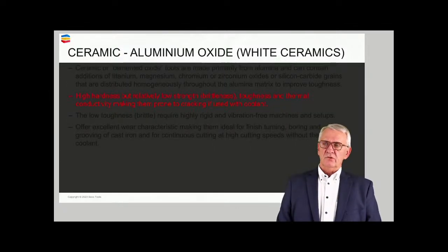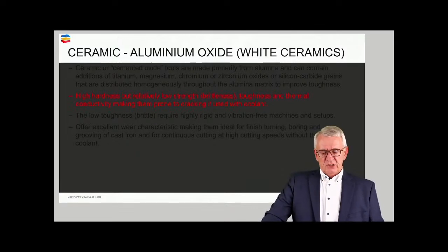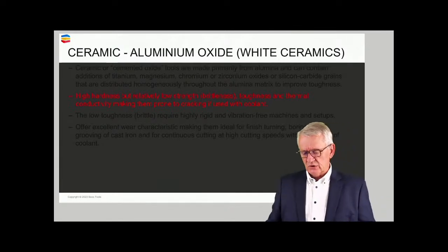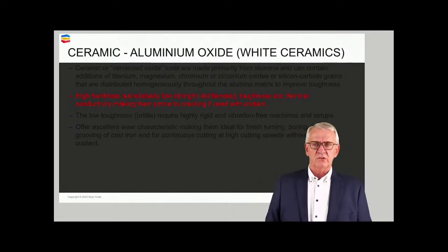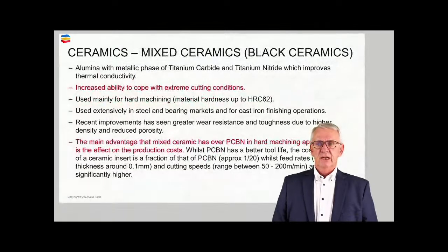High hardness with low strength, high brittleness, toughness and thermal conductivity. Those are the things you have to think about when you talk about the white ceramics. For your information, historical white ceramics were the first ones we used when we did machining with ceramics. And still, for a lot of people, and perhaps I should look at myself first, for me, ceramics is still that: it's good, but it's brittle, it breaks fast, and so on. One of the misconceptions, perhaps, that still limits the usage a bit today.